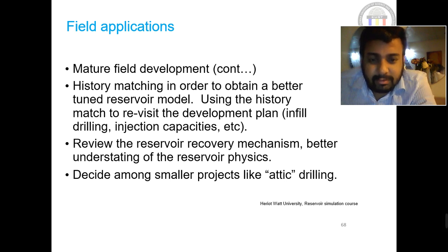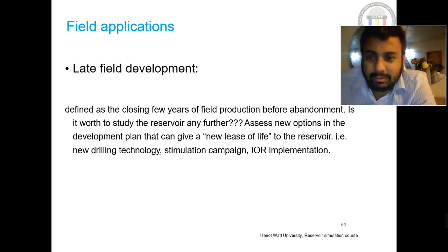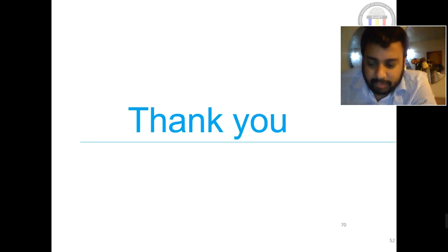Make sure that whatever model you run, it has to be history matched. And as I said, what is history matching? You have to compare your simulated results with the real field results. If both are in good harmony, if both are showing similar results, then you can predict the performance using your reservoir simulation model. Otherwise, garbage in will just produce garbage out. Your data has to be of good quality. You have to upscale it. You have to make sure that your reservoir model is history matched. Only then can you run the reservoir simulation.